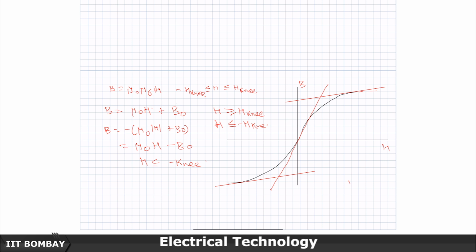To develop models, like for example the characteristics of the iron BH curve, you should be able to write equations, because once you write equations only then can you simulate it in a computer. And so this becomes a kind of art or a practice, and there is no one way of writing this equation.